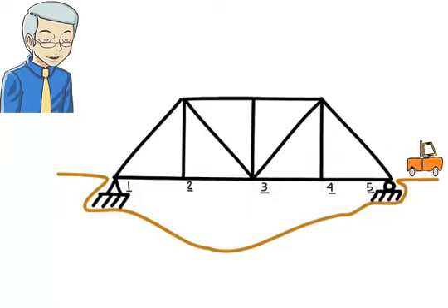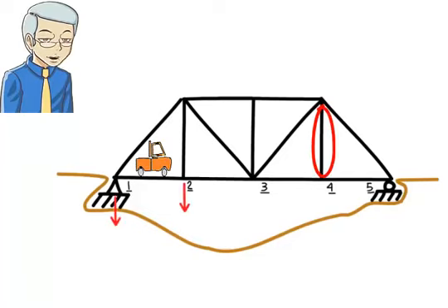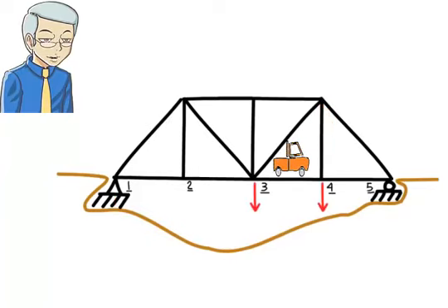The bridge truss must be analysed under each loading case. Note that a truss member that actually carries an axial force in one loading case may become a zero-force member in another loading case. For example, when the load is applied at joints 1 and 2, the vertical member attached to joint 4 carries no internal force. When the applied load moves to joints 3 and 4, the vertical member attached to joint 2 becomes a zero-force member.